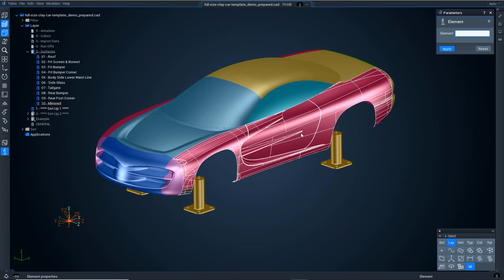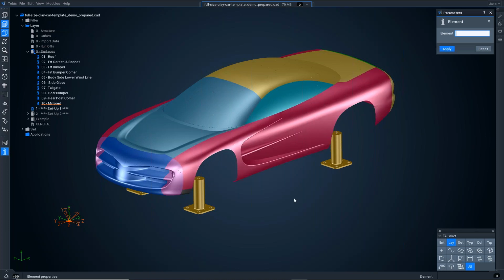Now this axis system is linked to the layer, as well as this surface data being also added to that layer. So not only can Tebis separate information by layer, we can also separate by color and by names as well. What we have here then is each of these individual areas put onto individual layers so that the template knows exactly where to find them. And then these axis systems are there so that Tebis knows how to machine them as well.